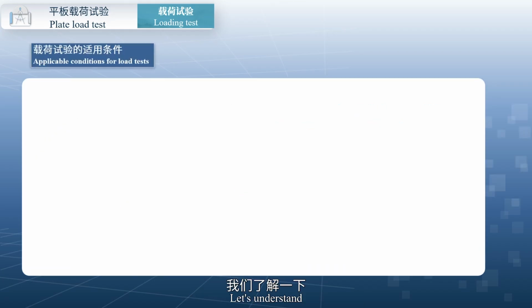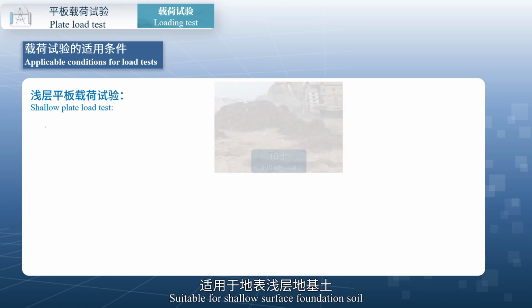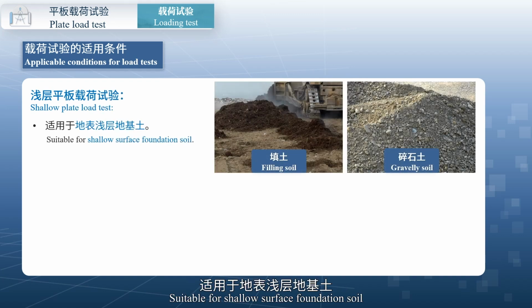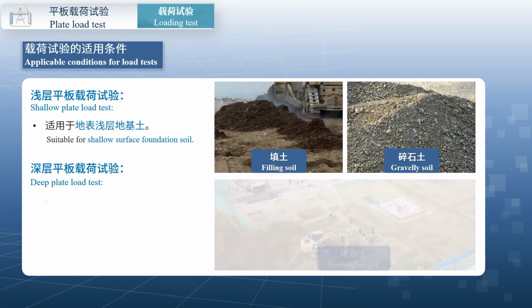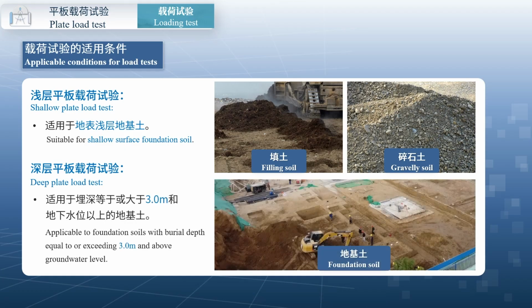Next, let's understand applicable conditions for load tests. Shallow plate load test. Suitable for shallow surface foundation soil, including various fills and gravelly soils. Deep plate load test. Suitable for burial depth equal to or greater than 3 meters, and foundation soil above the groundwater level.